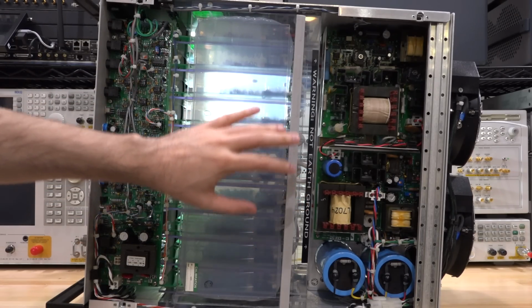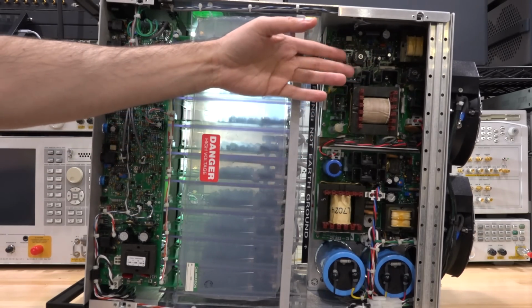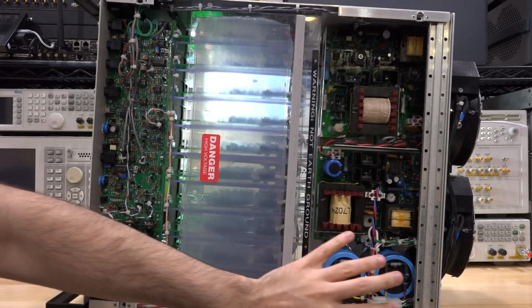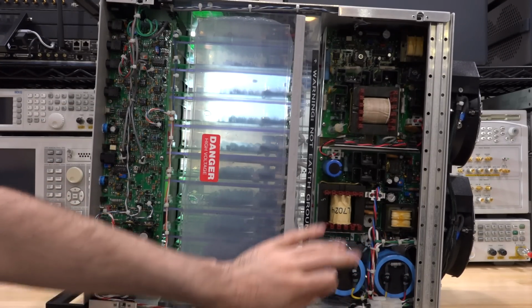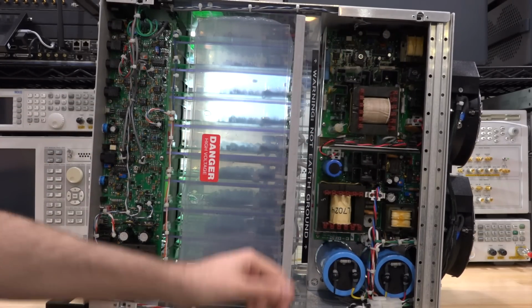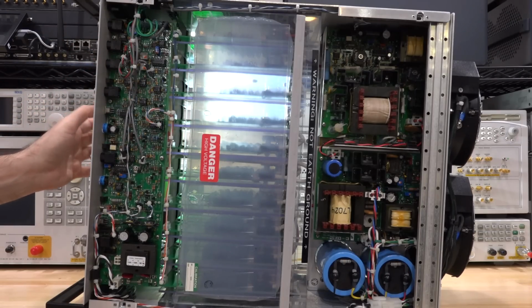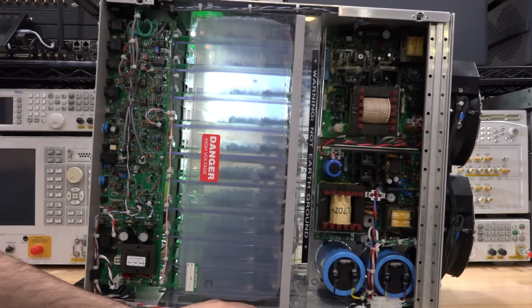Now on the right side, we have 2 big power supplies. One is a negative and one is a positive. I think this is a positive power supply and this is a negative power supply. At the bottom there is some rectification, 2 big capacitors to smooth everything out and provide a good stable power supply to these 2 other power supplies, because this thing is obviously not running at 100% efficiency. So if it can put out 400 watts at high voltage, it's burning a lot more overall. So it's a pretty power hungry instrument.